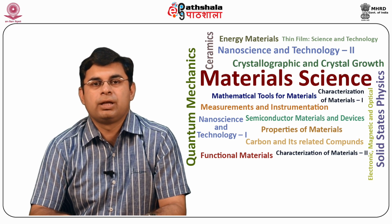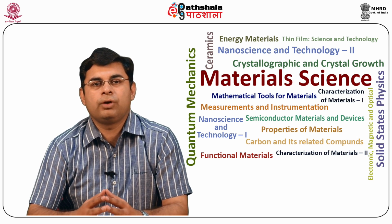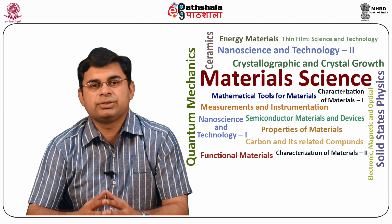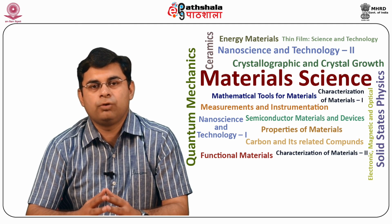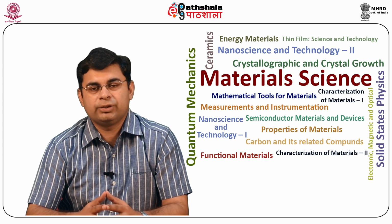High resistances: resistances above 100 kilo ohms are included in this class. The measurement of high resistance is required for determination of: A, resistance of high resistance circuit elements; B, insulation resistance of components and built up electrical equipments of all types; C, volume resistivity of the material; D, surface resistivity.